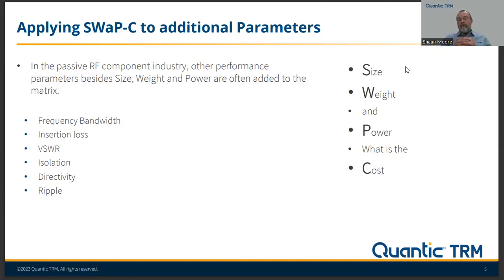You're not going to want to use a 2 to 18 gigahertz coupler, because as you go across that frequency range, you're going to have to have multiple sections to cover that, as opposed to a single section that you can use and still cover your needs. Your insertion loss will be much higher. Chances are your VSWR won't be as good, and it's certainly going to be a lot larger and a lot heavier. If that part is going on something like a spacecraft, then the broadband part is actually a detriment because of the other parameters that it affects.